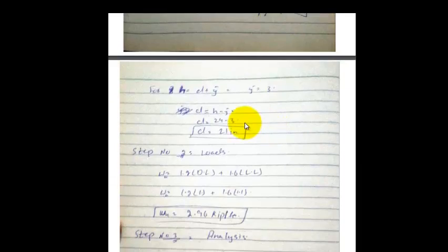So move to find the effective depth of that beam. We have the formula that h is equal to d plus y prime. We got y prime is equal to 3 inch. So d is equal to h minus y prime. d is equal to 24 minus 3. We get the answer, which is 21 inch. The effective depth of the beam shall be 21 inch. But these all are assumptions.